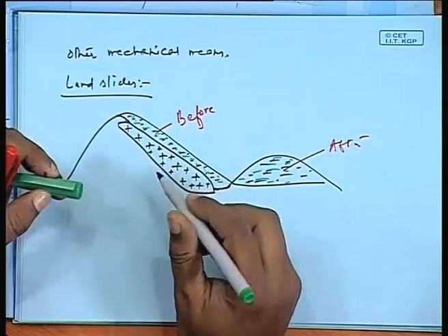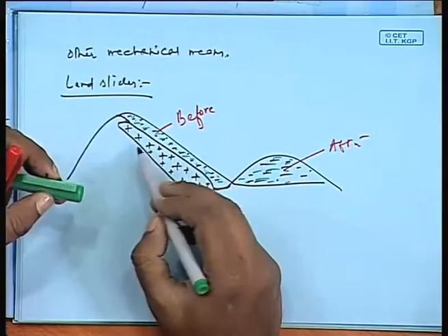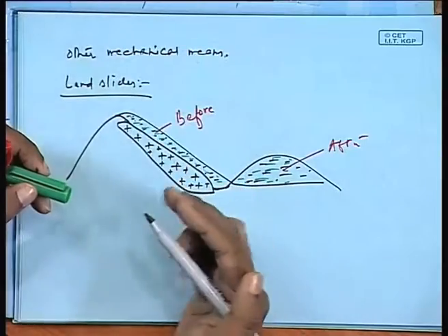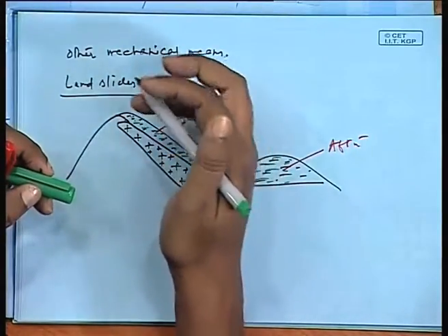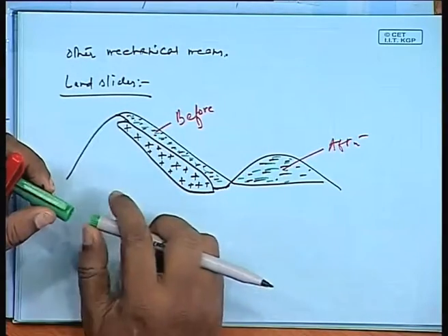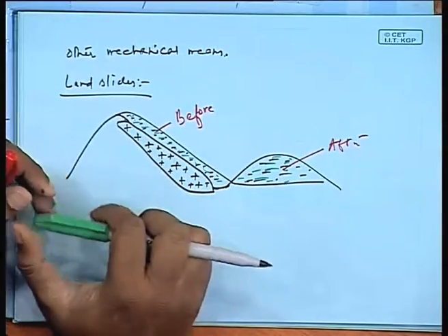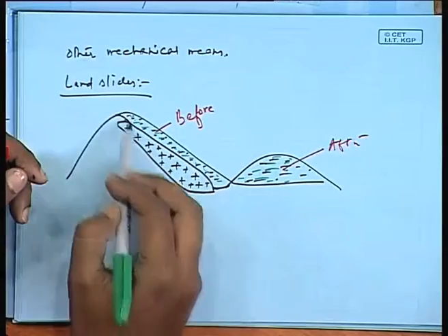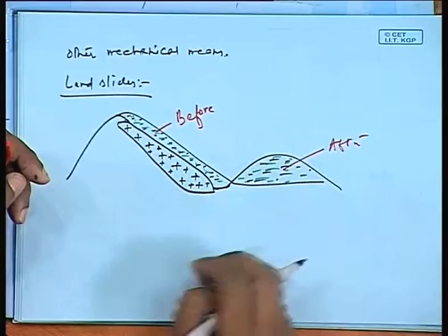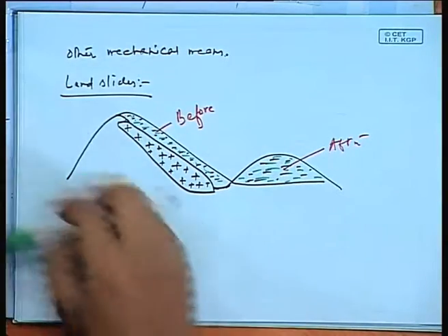The reasoning is somewhat different, in the sense that this is particularly in the mountainous region, when there are large rock surfaces just below the sand and soil surfaces, the coefficient of friction reduces due to heavy rainfall, and that allows the soil surface to move from the top en masse, and this is how it would look at the end. So this is what is a landslide.